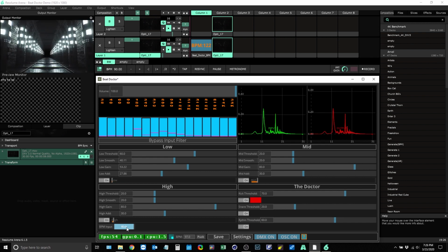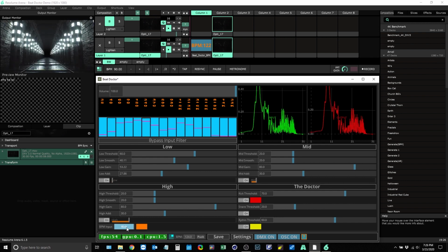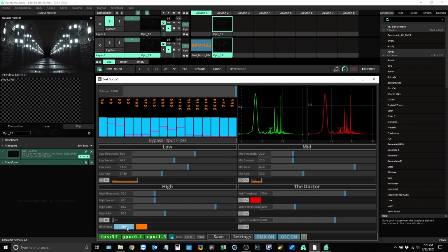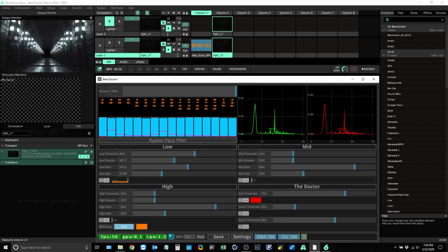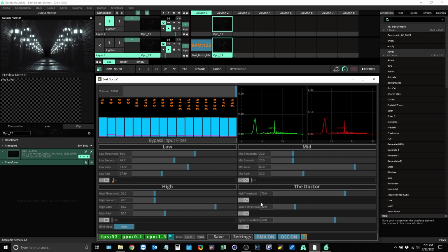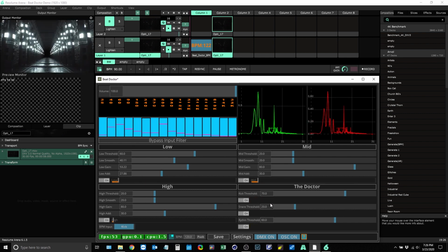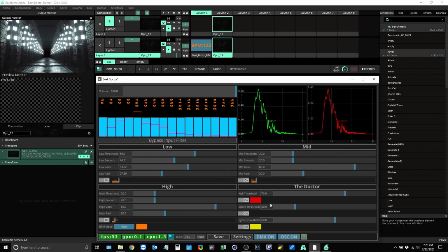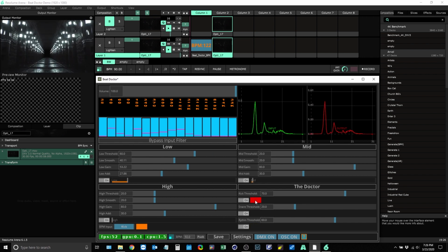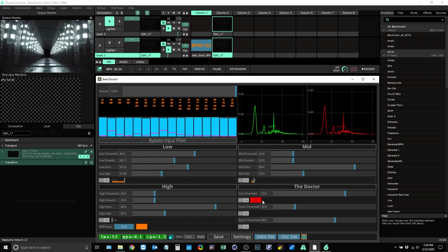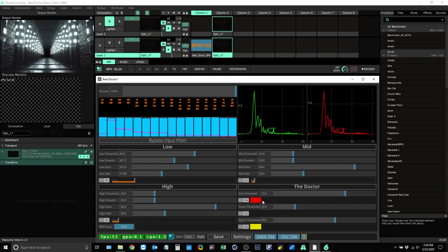You can get a lot of false positives. It's not really an exact science, or it is a science, but the way it works is you're basically measuring the time between each beat to determine what the BPM is. The problem, though, is if you get a false trigger, that's going to jump that number up quite a bit because it read something that was not intended to be the beat.